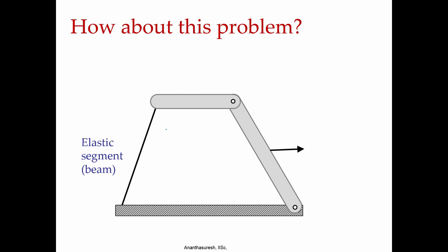How about this problem? What I have changed now is that it was fixed here in the earlier slide, it is also fixed now. In this case, because of that force, let us say in that direction here, because we are not allowing it to rotate there, there will also be a moment that comes over here.